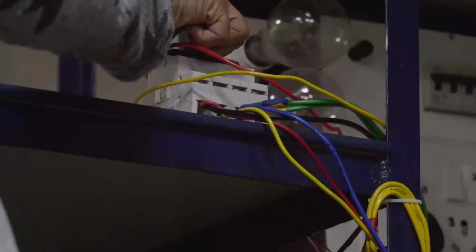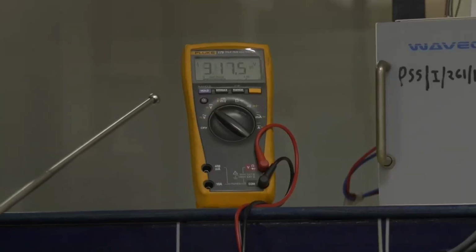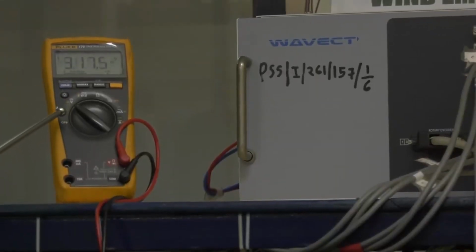The main and the rotor branch circuit breaker is switched on and the DC link is charged initially to 317 volt. The power amplifier voltage information is passed to the PLL of the FPGA controller to extract the grid phase angle. Then we enable the phase locked loop and check the reference theta with the phase A voltage.